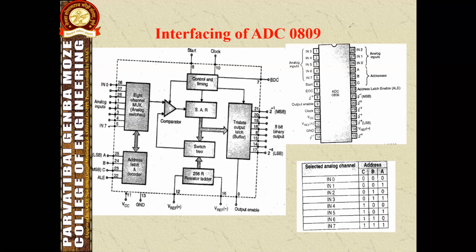Start and EOC. We have to enable the start input to begin the A to D conversion, and a pulse is to be given to the start pin to start conversion, and the end of the conversion is indicated by the EOC output.